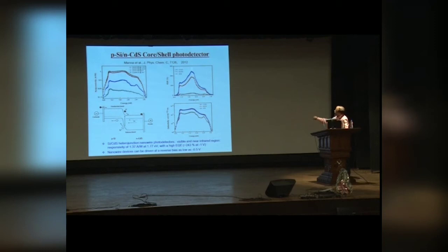That's what exactly we get when you calculate the external quantum efficiency. So, this gain comes not from really the gain in the device, it comes from the extra electron injection from the so-called cathode material, which has been shown by the band diagram here. So, this is N-cadmium sulfide, P-silicon, you have got a conduction band offset and valence band offset, and of course the minority carrier from these electrons goes to the anode, and this electron mobility is much higher than the hole mobility of cadmium sulfide.